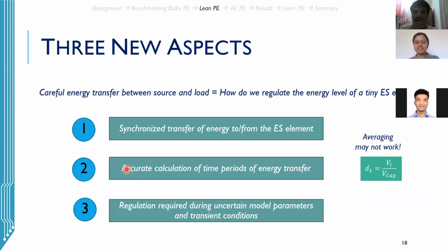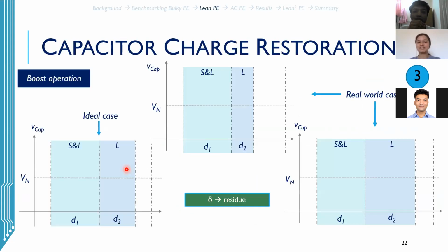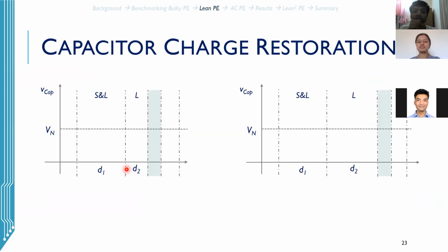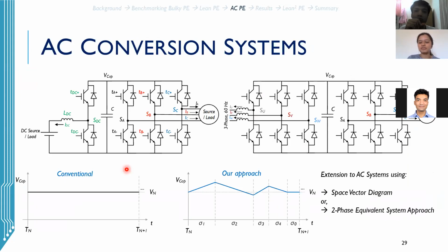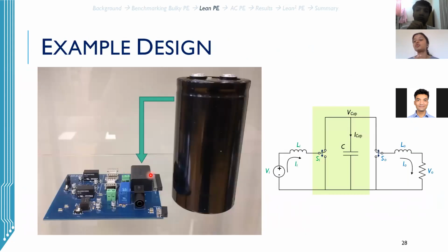In fact, I agree, because the interesting thing that happened, like I showed in the prototype, was that when we were trying to find this capacitor value, we wanted to use 2 microfarads of capacitor and say that we have a stable operation. And we were able to even find a capacitor which can handle that much ripple current. But the problem was that it was not available. There was a part which existed, but the requirement for such small capacitors with higher ripple current is so low that we couldn't find it in the market. Right.